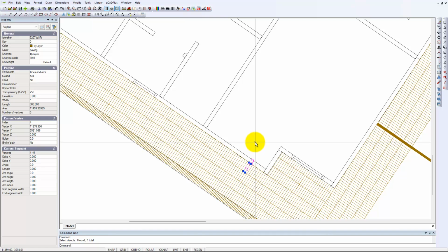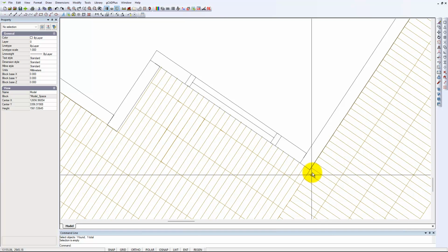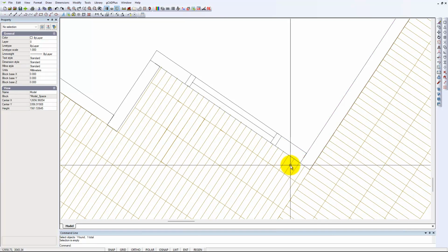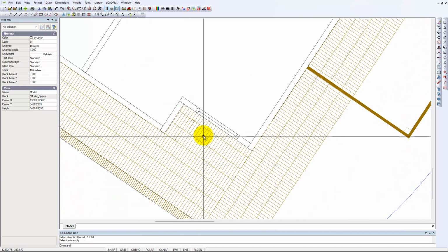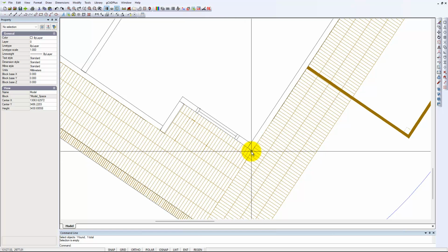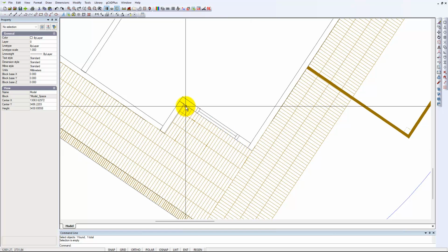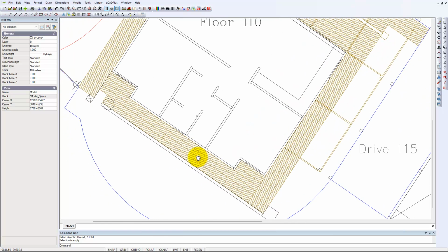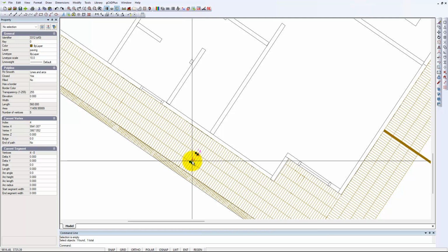If I could find a polyline that covers that whole area, and so far I can't, what I'm looking for is a polyline that traces around here. So if I were drafting here, I'd set a polyline, a new one, probably set a different colour so I can pick it easily, and then trace around the whole of that area, and then apply a hatch rather than lots of individual rectangles.